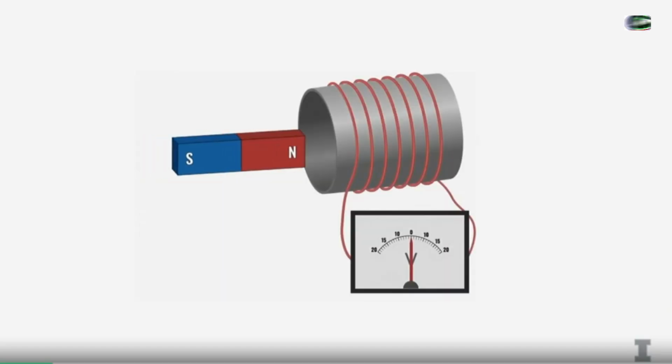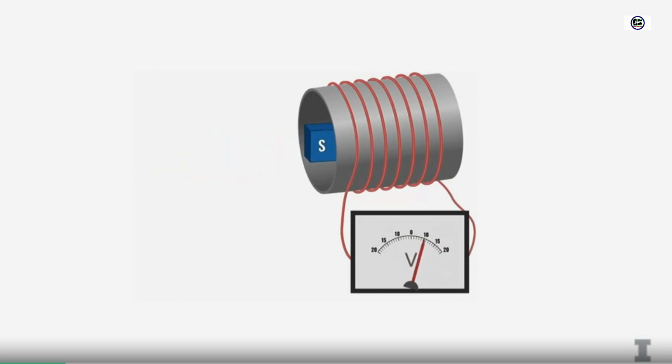As you may know, if you have a conductor and you expose it to a changing magnetic field, that changing magnetic field can induce a current through the wire. And the opposite can happen too. If you have a wire, that can create a changing magnetic field as well. So the problem with this is if you have a wire and it's transmitting information and it's exposed to changing electromagnetic interference, that can generate noise in the wire, make it harder for you to read the signal. So it turns out this happens a lot. And it's something we have to deal with, especially in IoT settings, where you have these devices everywhere.